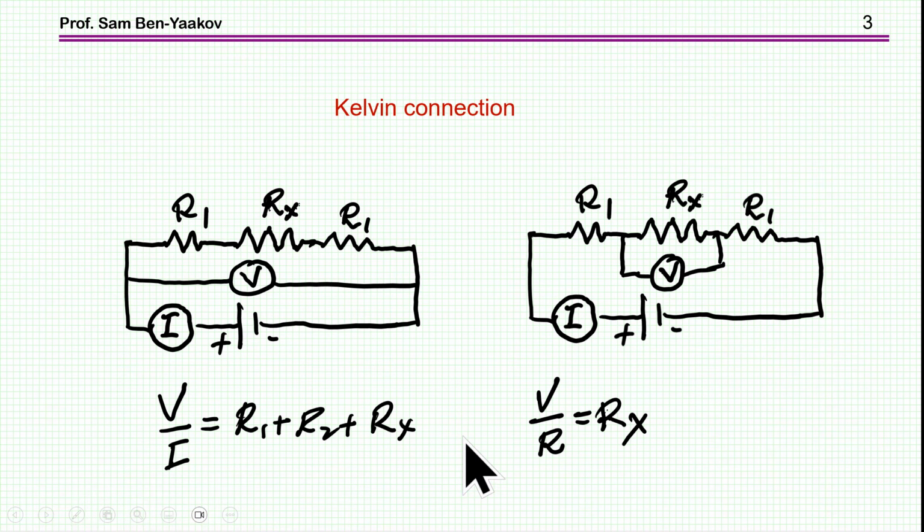Let's start with that. If we want to measure, say, the resistance of a resistor here, we can inject a current and then measure the voltage across these terminals. The problem is that if the resistance is very low, then the interconnection can contribute quite a bit to the resistance. So in this case, you're going to get an error. So the idea of a Kelvin connection is that you're injecting a current and then you measure the voltage just across the resistance itself rather than an interconnection.